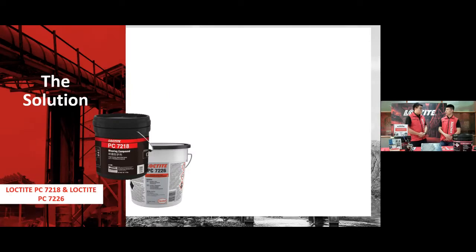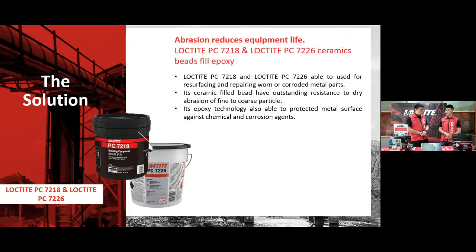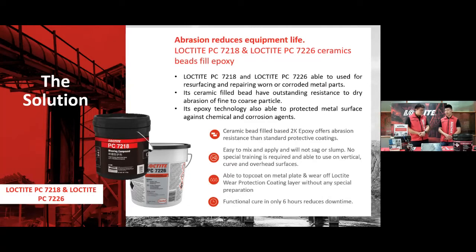Okay, like what you mentioned, for these dry, fine, coarse abrasions, we can use LOCTITE PC 7218, what we know as LOCTITE Wearing Compound, or LOCTITE PC 7226, what we know as LOCTITE Wear. The reason why both of these products are suitable for dry abrasive situations is that they are filled with ceramic fillings, and these ceramic fillings have very good, outstanding resistance towards abrasion.